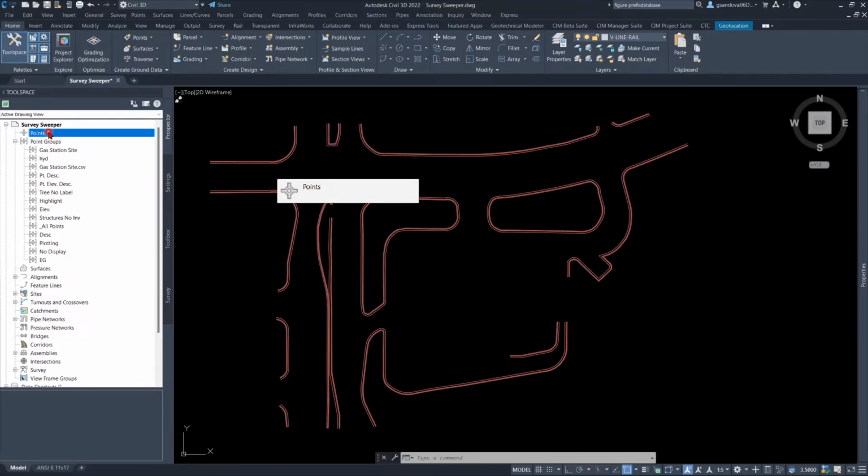If we bring them in through these 3 different tools I just showed you guys, we won't have our line work processed. We can bring them in, we can use them for surfaces, we can use them for whatever we need to use them for. But again, our line work won't be processed. The only way we can get our line work to process is if we bring them in through our survey database. So it's not wrong to bring them in through these 3 different ways, and you can still use them. You can still create 3D polylines, feature lines, etc.